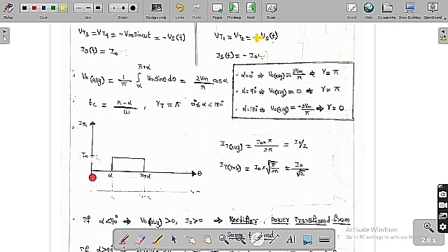So now, I want to draw the thyristor current. Let me take the thyristor T1. I want to figure out what the current through the thyristor is. Thyristor T1 is going to conduct only from alpha to pi plus alpha. So from alpha to pi plus alpha it is on, and for the remaining time it is off, open circuit. Therefore the current is equal to the load current, so I T1 is equal to I naught, only from alpha to pi plus alpha.